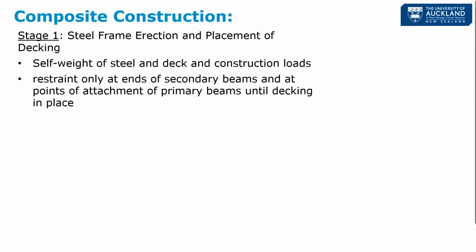But the big thing is, and what we will see in a lot more detail when we start looking at the design of beams in bending, is that the restraints of the secondary beams are only going to occur at the points of attachment to the primary beams until we get that decking in place.